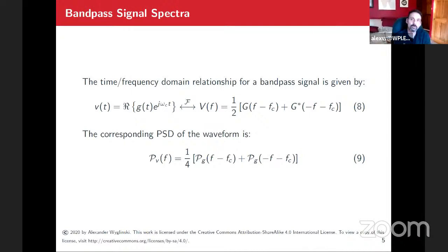So that's really critical. The receiver can't operate at passband. It cannot just say, oh, extract information at FC and minus FC. That's going to be very expensive for a number of reasons, which I'll talk about later on. You have to demodulate back down to DC and then take the baseband signal and remap it to the message signal, okay?